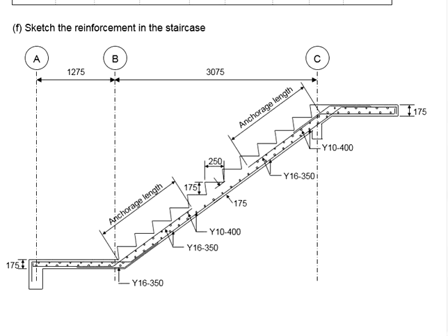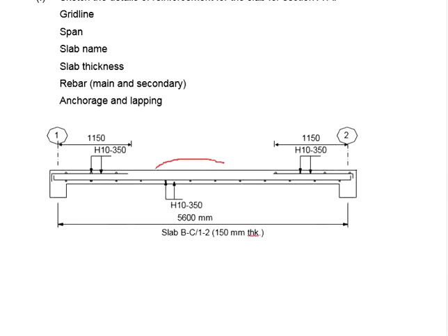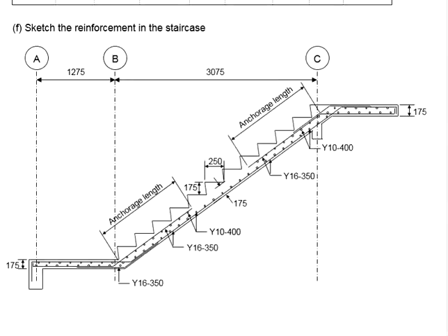Normally, when it comes to the arrangement of the reinforcement, a staircase requires both top and bottom reinforcement. You can do curtailment in order to save the amount of reinforcement, similar to a slab. When the design does not require any compression rebar, you can release the amount of reinforcement. Now the question here is, where shall the reinforcement stop?